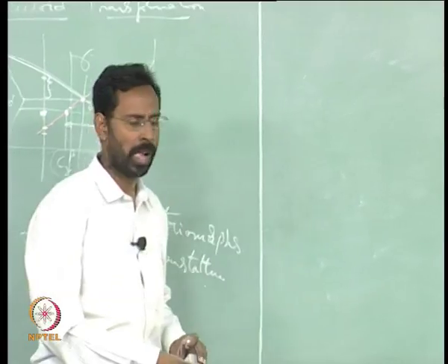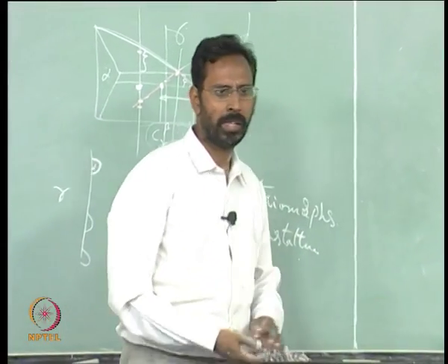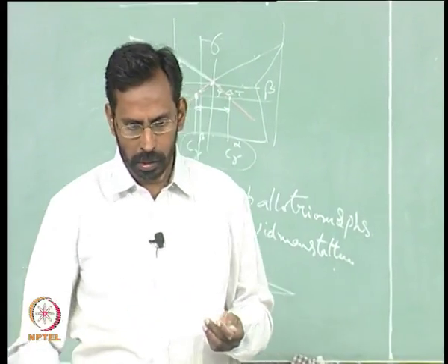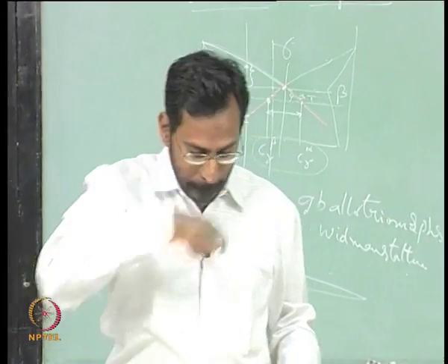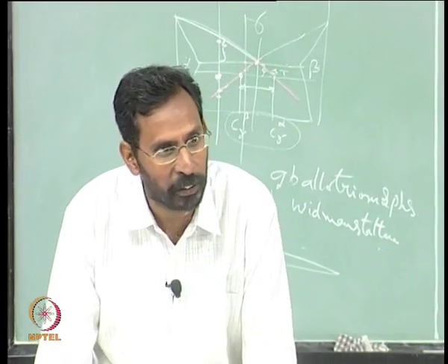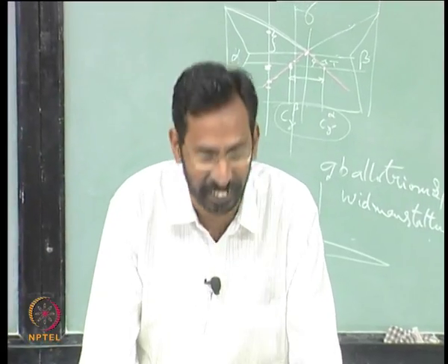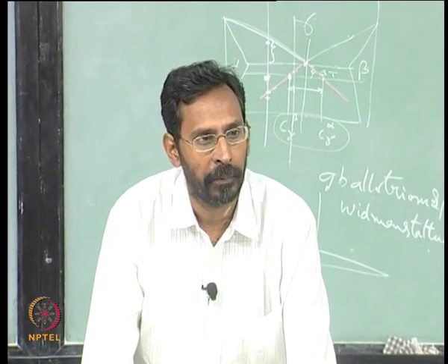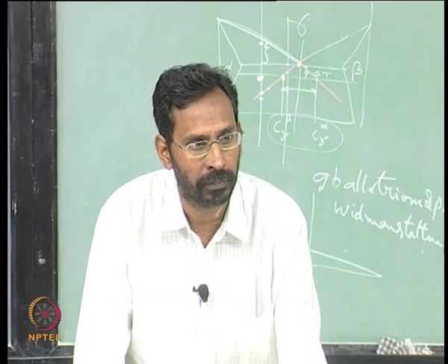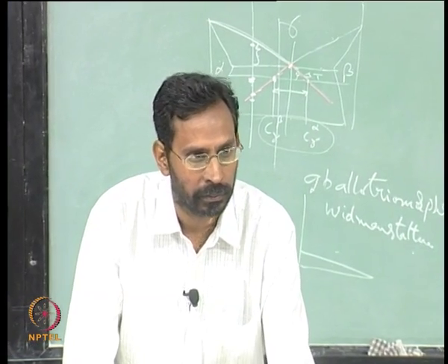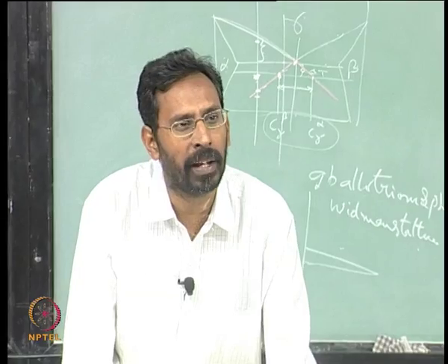In iron carbon alloys, we are getting chunky carbides because of the interfacial energy of cementite and carbon. Yes, that is not in eutectoid. Please, eutectic. Yes, tell me. The same interfacial energy logic has to be applied for eutectoid also. Why are we getting a difference? Yes. The reason is because it is a solid state.